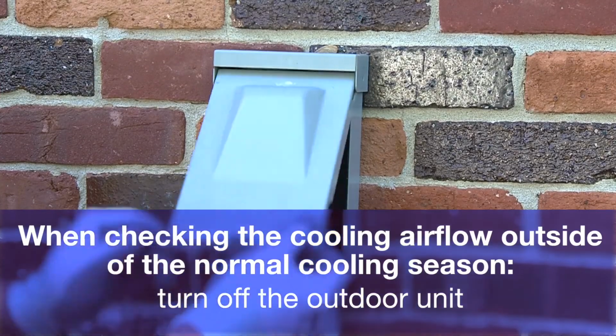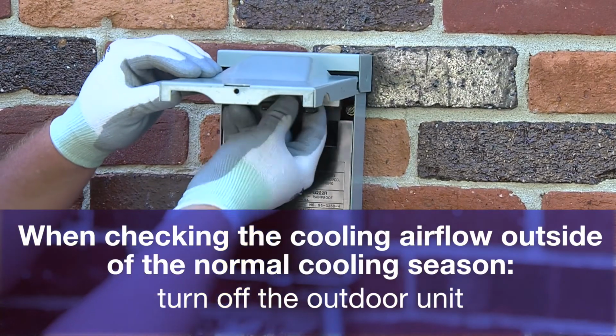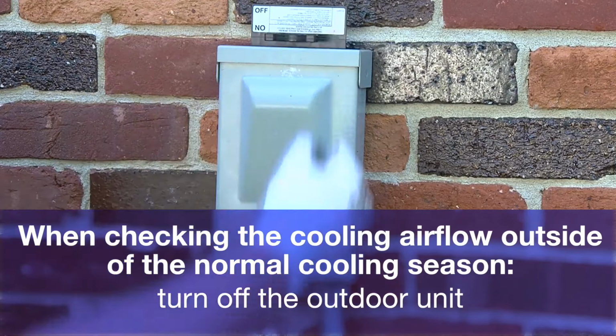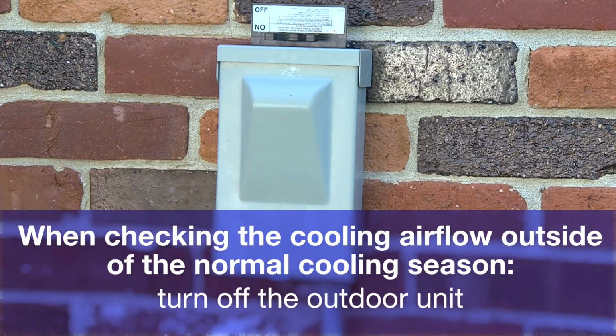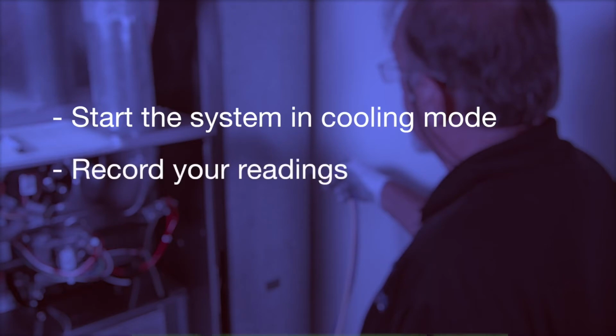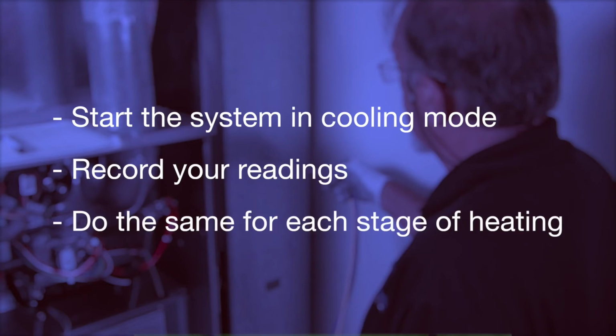Also, when checking the cooling airflow outside of the normal cooling season, turn off the outdoor unit either at the breaker panel or the unit's disconnect panel. This will prevent the unit from starting and possibly slugging the compressor. To begin taking your readings, it is best to start with the system in the cooling mode. Record your readings in the cooling mode, and then do the same for each stage of the heating mode. This way, you get a true picture of the equipment's airflow performance.